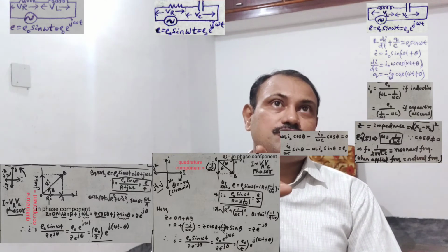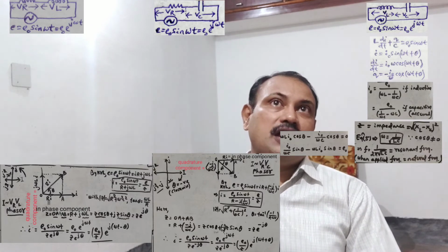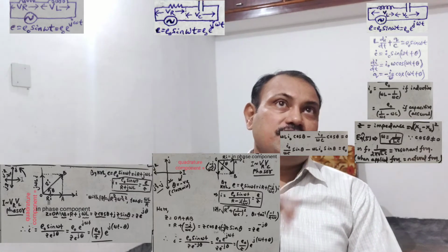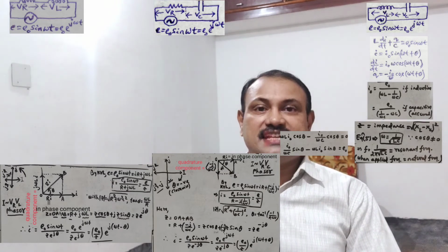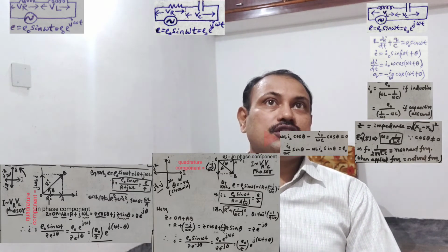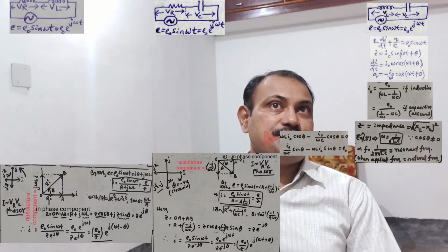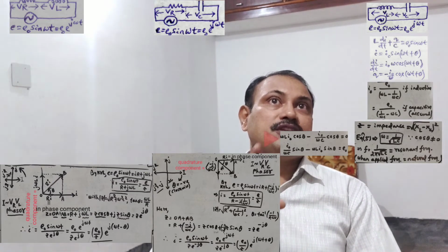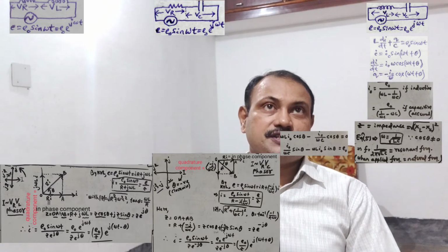impedance, which is equal to the square root of (XL minus XC) whole squared. And here, if you see equation 5, omega is equal to 1 upon root LC, because cos theta cannot be 0. So therefore, the frequency, which is equal to 1 by 2 pi square root of LC, is called the resonant frequency, where the applied frequency is equal to the natural frequency of oscillations.